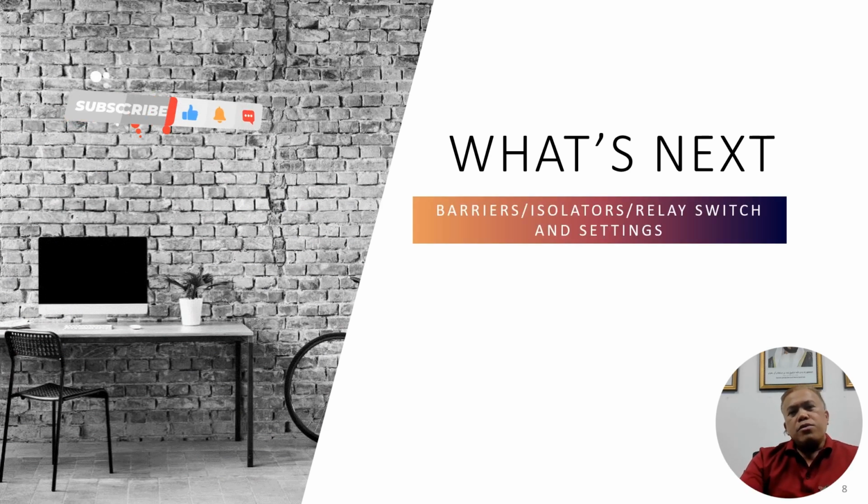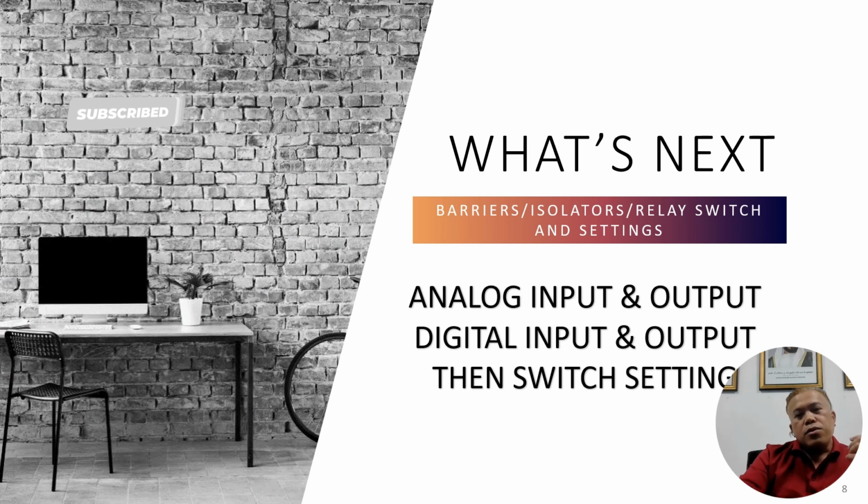After that, barrier, isolator, relays, switch and settings. You need to check analog output, digital input and output, and then switch settings. And then we are ready to close the punch list and dispatch all the panels that we already inspected.